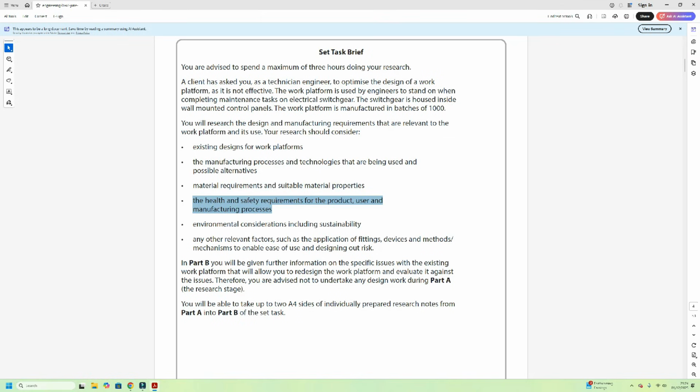Well, someone's got to lift those plates up. Now, a 3mm plate at that sort of size, half a metre by half a metre, is going to be heavy to handle. So you now have to think about manual handling, and obviously PPE for the manufacturing process: eyes, breathing equipment or extraction fans. If you're welding, there'll be extraction fans on there. Health and safety of, let's say, welding, painting, laser cutting, plasma cutting, like this is.